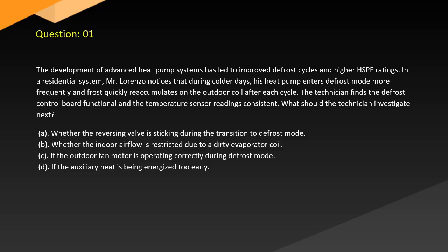Question 1. The development of advanced heat pump systems has led to improved defrost cycles and higher HSPF ratings. In a residential system, Mr. Lorenzo notices that during colder days, his heat pump enters defrost mode more frequently and frost quickly reaccumulates on the outdoor coil after each cycle. The technician finds the defrost control board functional and the temperature sensor readings consistent. What should the technician investigate next?